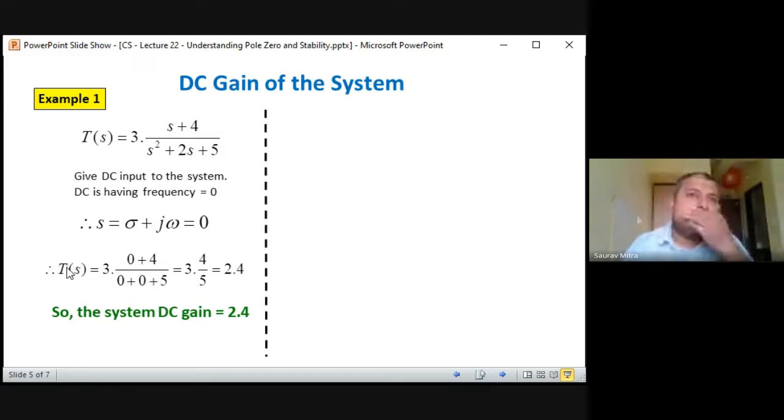If the square wave has a frequency of 100 hertz, the Fourier series says that this signal is a function of a lot of sine and cosine waveforms of multiple frequencies. If I give you a 100 hertz square wave of certain amplitude, it can be constituted by sine and cosine waveforms of frequencies 100 hertz, 200 hertz, 300 hertz, 400 hertz, up to infinity. So 100, 200, 300, 400, 500, 600, 1000, 10,000, all of these are called multiple frequencies or higher order harmonics of the baseband signal.